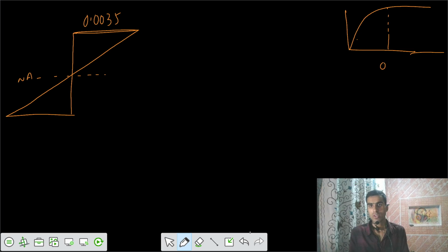So up to the strain value of 0.002, we have parabolic nature for the stress block, and after that we have a constant value of stress up to the strain value of 0.0035. At this value we have the cracking of the material.